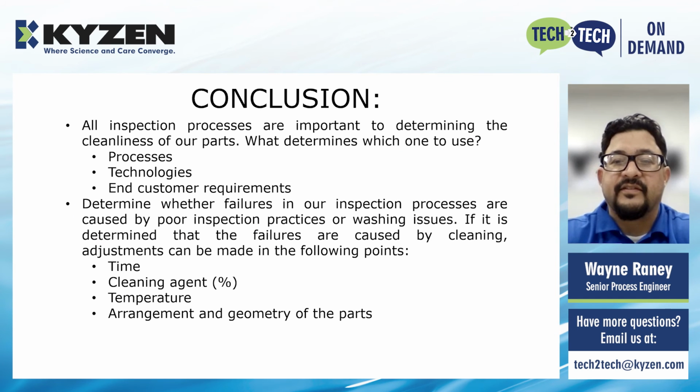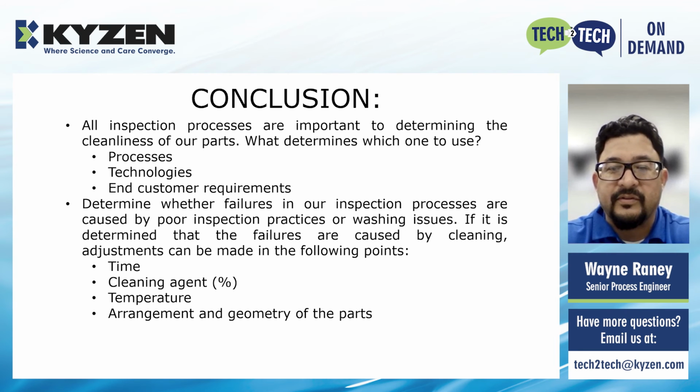So of the four methods of inspection, how can we determine which method to use? It depends on the process. For example, if our goal is to clean a part in preparation of placing an adhesive label on it after washing, then you don't need to purchase expensive equipment such as a particle counter. But if you're talking automotive, then you want to utilize all the inspection methods.